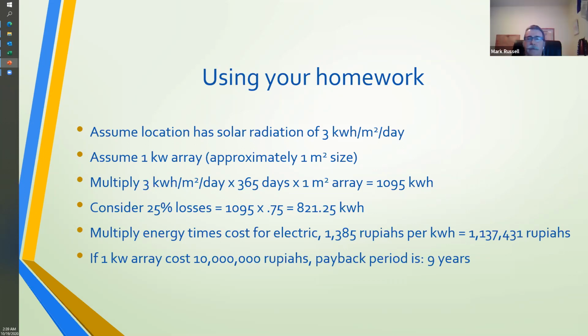I did two calculations. First, I calculated the size of my roof. I got 160 square meters. The dimension of the solar panel itself is 2 square meters. So the potential solar panels that I can use is about 80 panels.